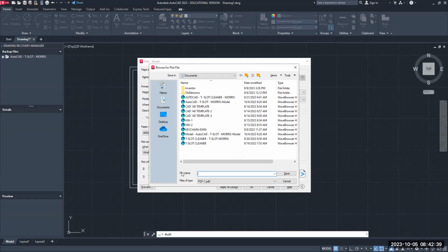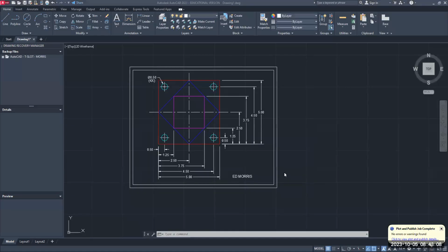So here's how you save this, folks. Type in capital EX, -2, -10, and then dash, put your last name. EX-2-10 and your last name, and make sure you know what directory you're saving it to. Select save. And there's your PDF. The nice thing about PDFs is somebody does not have to have AutoCAD. They can open up your drawing.